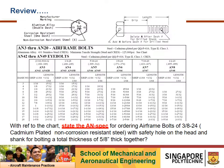Okay, let's look at this review question. Referencing the chart, state the AN spec for ordering airframe bolts of 3/8-24. 3/8 is the diameter, 24 is threads per inch, and the required material is cadmium plated non-corrosion resistant steel, and we need safety holes on the head and shank for bolting two materials. The total thickness is 5/8 inch.